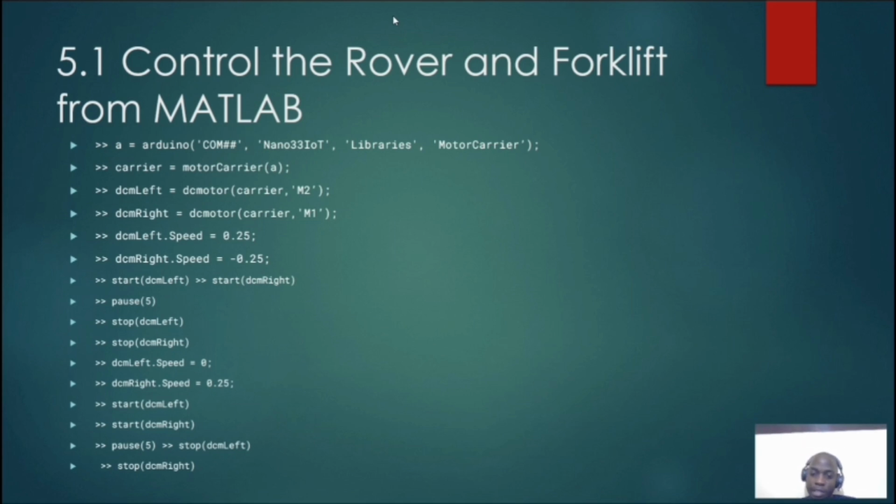The MATLAB live script handled our initial setup, as you can see from the slide. The crucial webcam image-based processing was done in the script. The core control logic for this project, however, resides in the Simulink model that gets deployed directly onto the Arduino Nano IoT board. The communication between the MATLAB environment running on our computer and the Simulink model on the robot happens seamlessly over Wi-Fi with a TCP/IP protocol.